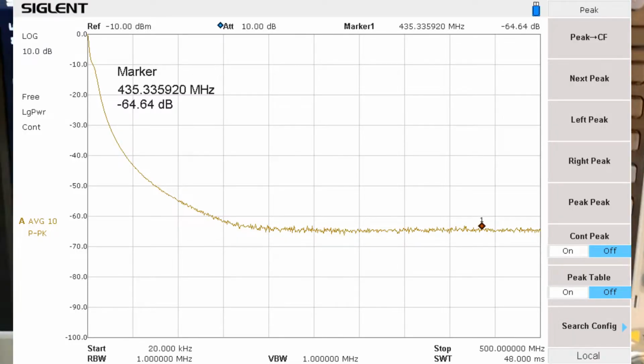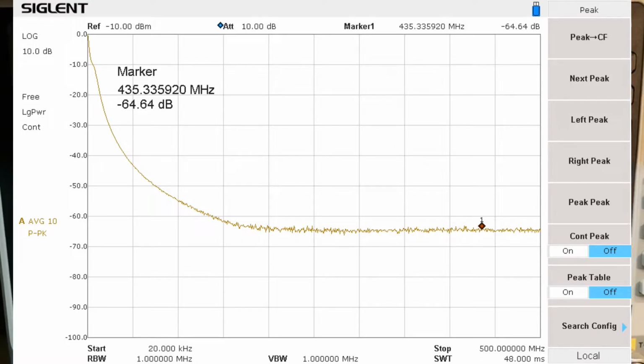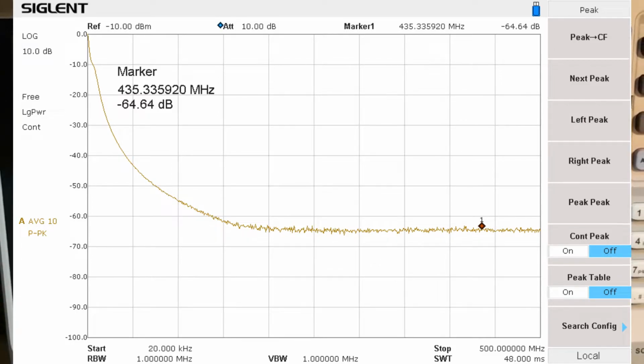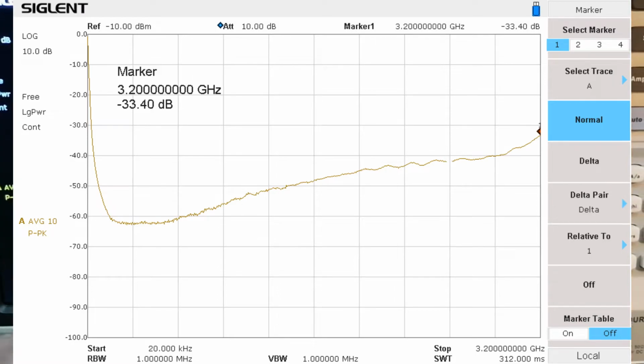So, I have reached the dynamic range of my analyzer in the setup and the calibration that I have done here. Also, you will see that this is exactly the same as no signal, and this is flat all the way up. I think we should maybe create a new calibration and do a full sweep. And also you will see that the capacitors that I used are a very, very low value. So that means I have almost no attenuation at very low frequencies.